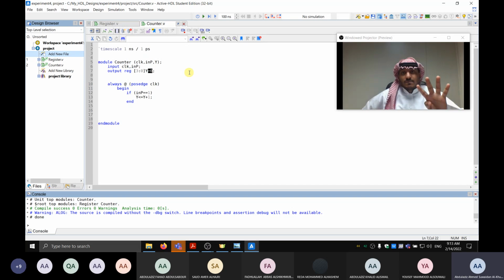So y is a 4-bit, and then you start adding up. So of course you will reach 1, 1, 1, 1. Yes, 15. So when you add another one, you see we have a 5th bit. We call it overflow. You study that. Yes, so we'll start over. Yes, it will overflow. The overflow, of course, there is nothing to be saved. It will be removed, and then these will come back to zeros. And then you'll start over. So when it reaches 15, you add 1, it goes back to 0. Okay, yes, there is no error.